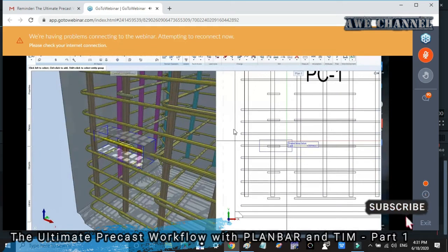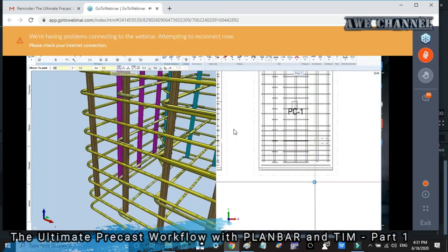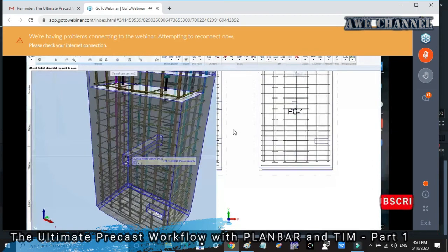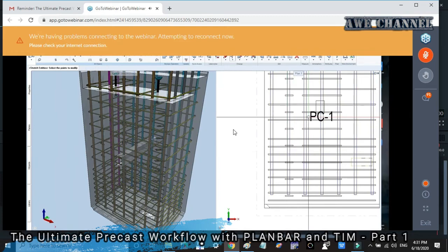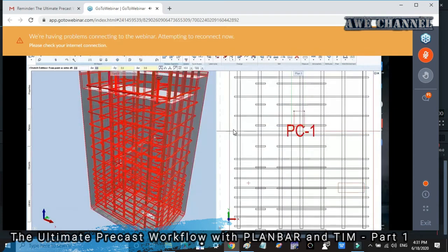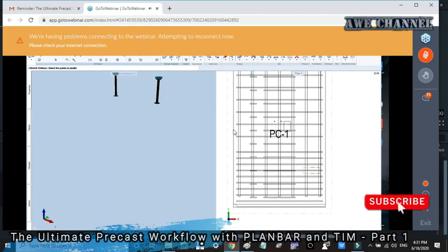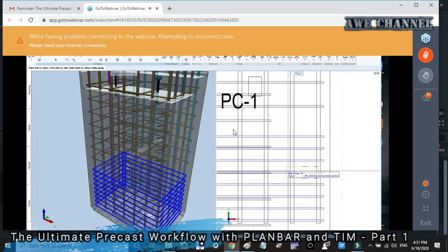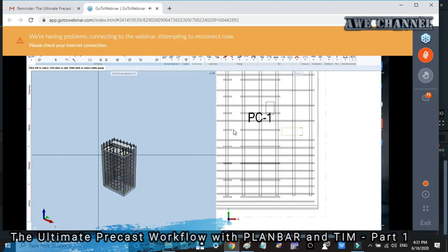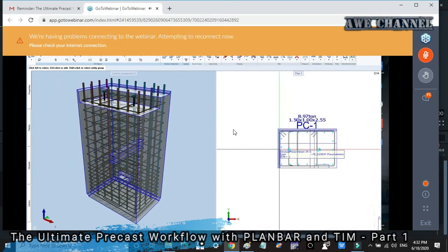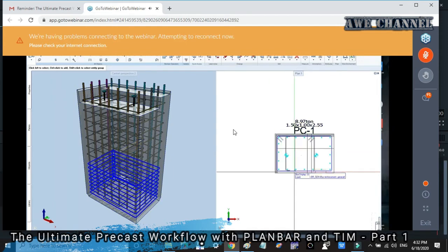So this one is called the modified precast element. You can still move this in any place that you want it to be. Compared to this one, it is already directly done using the 3D elements. So what you can still do is movement by stretching, but for the other one, it's not possible. It's still possible to do by just moving and clicking this shape linear fixture, and you can place it anywhere.